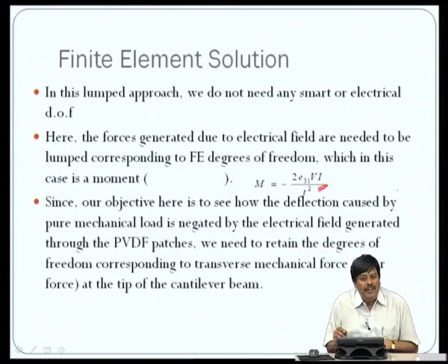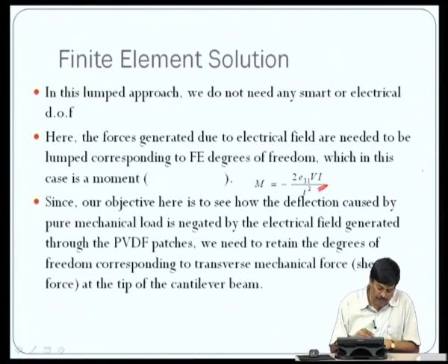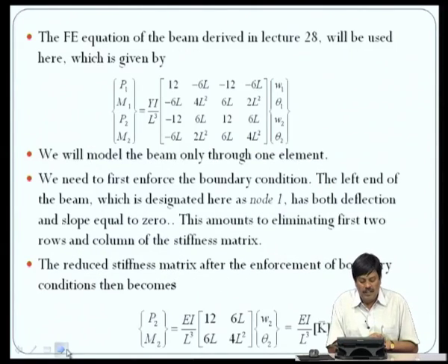Since our objective here is to see how the deflection caused by a pure mechanical load is negated by the electric field generated through PVDF patches, we need to retain the degree of freedom corresponding to the transverse mechanical force at the tip of the cantilever beam. So we go back to the stiffness matrix which we derived in lecture 28, which will be used here,